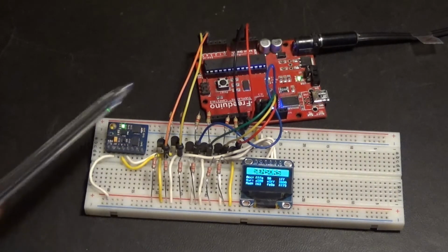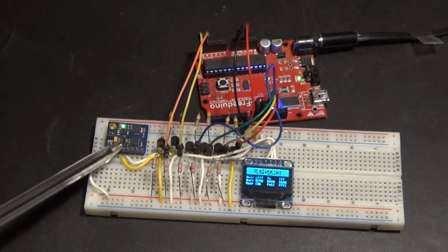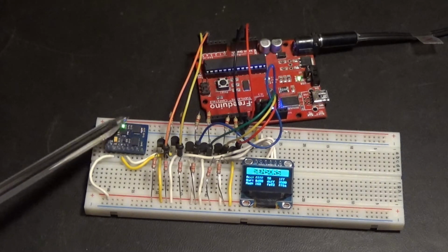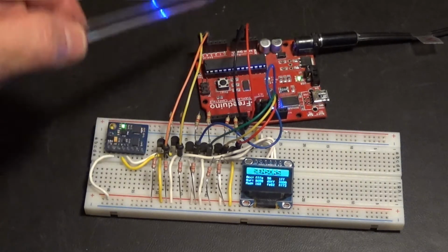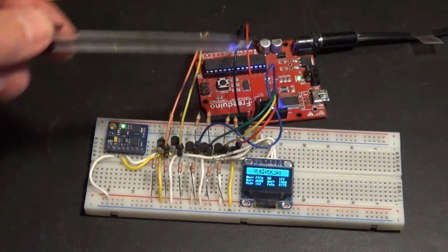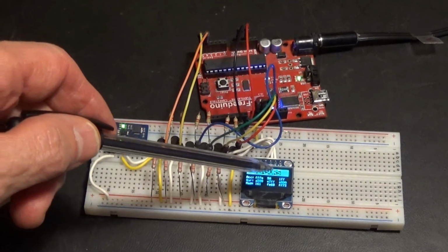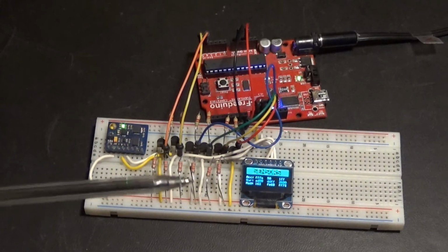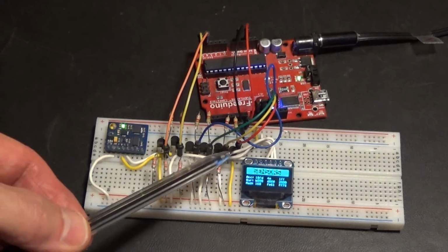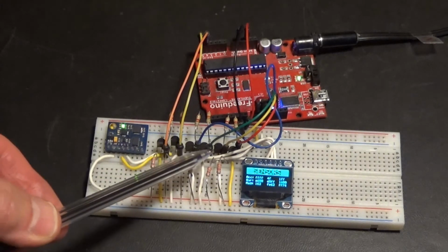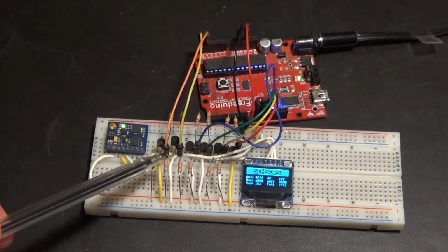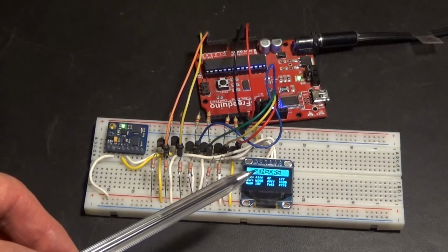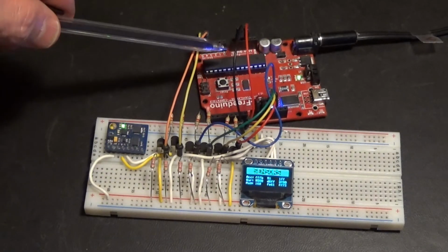bus. Everything else here is the same breakout board as in the previous video, which has the accelerometer, gyroscope, and magnetometer. This is still I2C, and it still communicates to the microcontroller with I2C, but the microcontroller is now communicating to the display with SPI. So this is a video about the SPI data bus. All this stuff in here, these are a bunch of field effect MOSFET transistors, and they're used for level shifting because this board and this display run on 3.3 volts and the microcontroller is running on 5 volts.